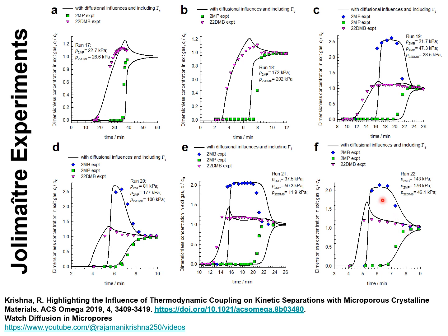So I conclude by saying that MFI zeolite is suitable for use in separation of alkane isomers. The separations are synergistic in nature because the diffusional influences serve to enhance the separations that is dictated by mixture adsorption equilibrium.